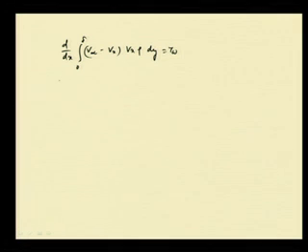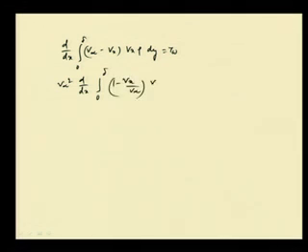Our momentum integral equation is d dx of the integral from 0 to delta of (V infinity minus Vx) into Vx into rho into dy, equal to tau w. So, this I was writing as V infinity square d dx of the integral from 0 to delta of (1 minus Vx by V infinity) into Vx by V infinity into dy, equal to tau w by rho.